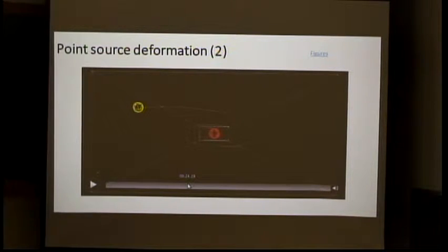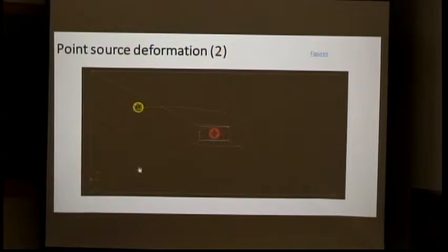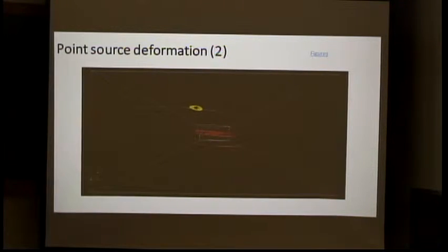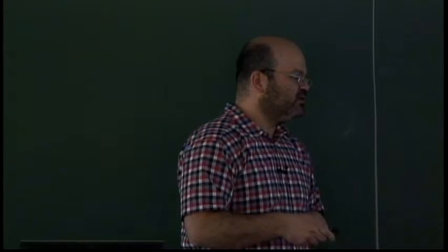Now we are looking at this from the injection plane, in the direction of the flow. When we let this go, it looks a little bit like a galaxy in the middle. But what's showing there is the deformation. The deformation of this yellow sphere is mostly due to stretching. As it moves, it stretches and becomes longer, while the one at the center mostly folds. So we have two different mechanisms: stretching in the yellow one and folding in the center.